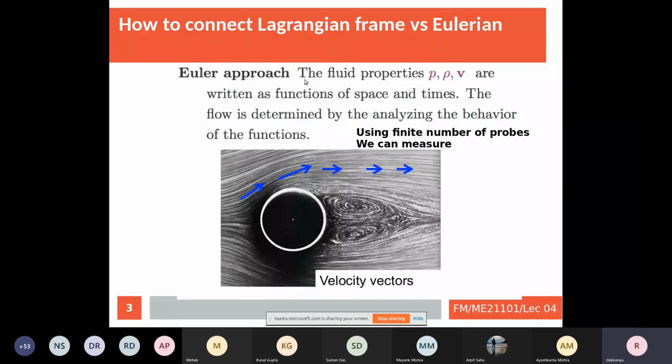So it is continuously heating the resistance, generating heat. You know how much heat is getting generated, with the I squared R t kind of formula. Now liquid flow comes, grabs the heat and goes away. Suddenly the temperature drops. You calibrate the temperature, then you know how much the resistance changed, then you backtrack it. Okay, this is the velocity with which the liquid is moving at that particular location. Now change the probe location from there to some other location, and some other location, or install multiple probes. So you track it through your computers, whatever means, and you will get the velocity.